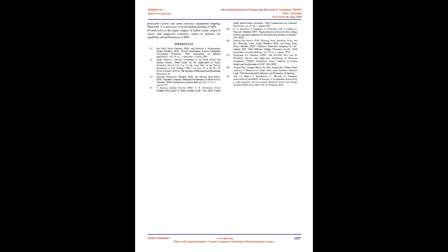Common mode filters. Factors responsible for failure are age, irradiation hardening, environmental degradation, insulation degradation, degraded connections, and defective circuit. Failure of the filter produces dielectric breakdown in capacitors, insulation breakdown, and inductor arcing. Use high resistance insulation; proper maintenance also helps to know whether any module needs to be replaced or not.